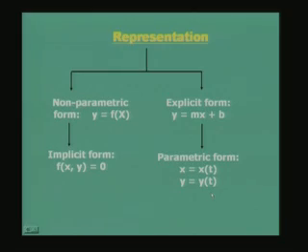Before we go on to discussions of various parametric forms, at least we know a few simple examples of curve representation. Let us say take the equation of a circle or an ellipse, which we have already used so far. We have used in 2D the equation of a circle and an ellipse, and those points lie on a plane. But a curve could exist in 3D as well. In fact, the circle could exist in 3D. The points on a circle lie in a plane. It's a two dimensional distribution of points, but if that plane can be visualized to lie anywhere in 3D, then we also have a curve in 3D.